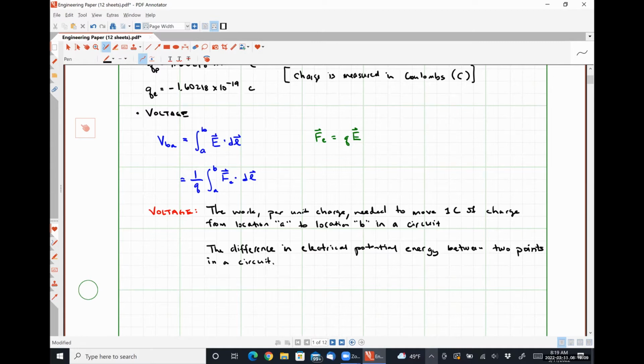That's going to be something that tends to trip you guys up when we get into our circuit analysis over the next several days. So I just want to introduce that now. Voltages, we'll find, are effectively what gives the push to cause current to flow, but it doesn't necessarily mean that current is flowing. We can have a strict difference in potential without a flow of current if we have a way to store charge. Okay. All right, so